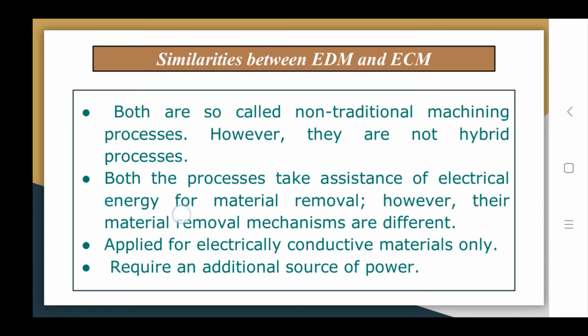However, their material removal mechanisms are different, and this should be noted. Then they can be applied to electrically conductive materials only. For non-conductive materials, a coating strategy can be adopted in some cases, but process capability and accuracy will not be satisfactory.